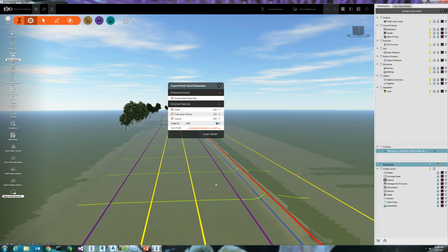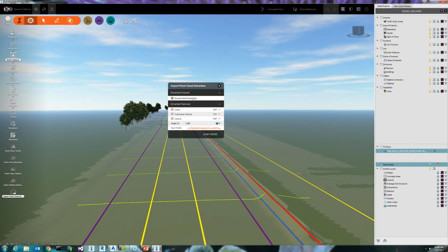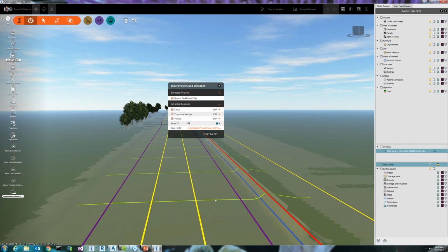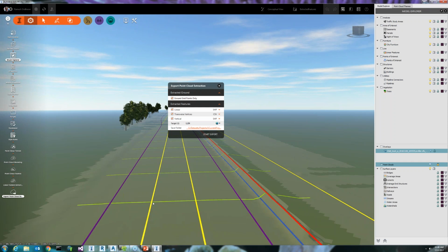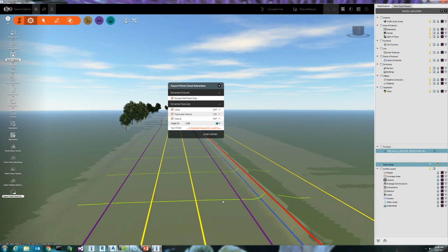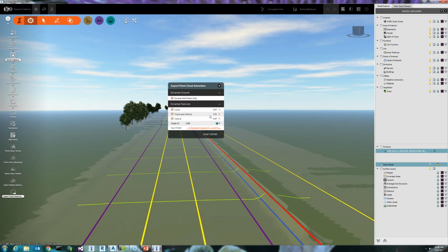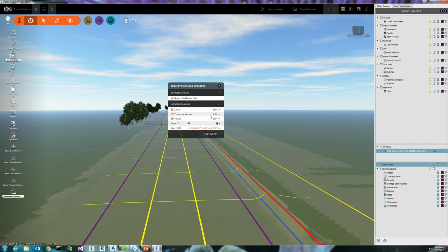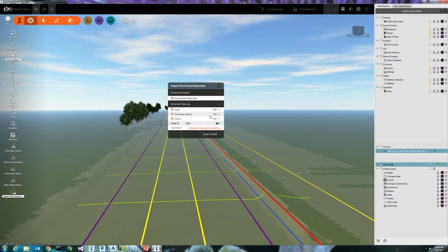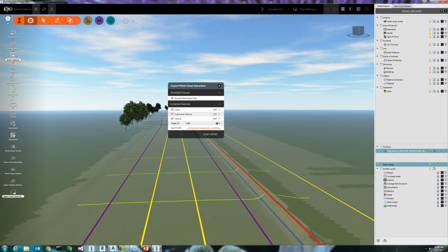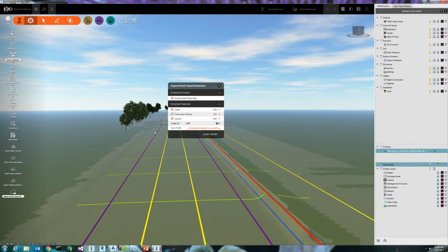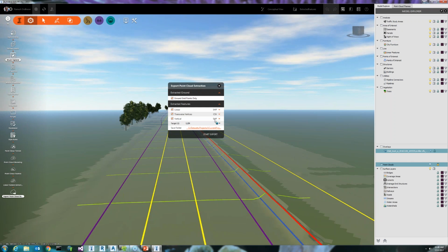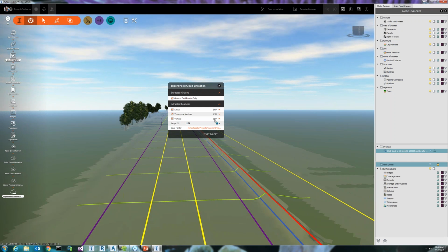Software can classify. We just classified this in a few minutes. You can create a grid of ground points. All the linear features along with the attributes, feature codes, everything you can extract as a linear part. Some customers like the transfers, some customers might not use it, so we kept it as optional. You can take it as a CSV file, you can take it to Civil 3D, you can augment your surface. The vertical features, all those trees, traffic lights, signs, street lights, you can actually take in as a 3D point shapefile. You can go wherever you want to go with it.